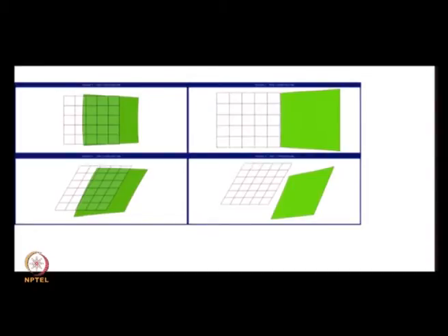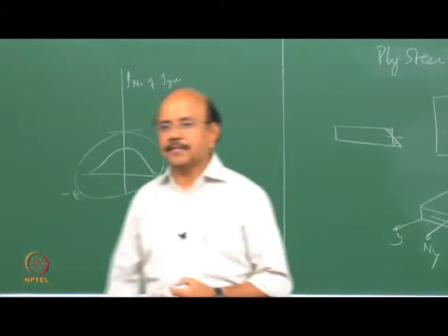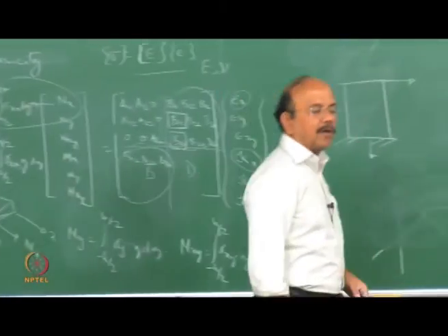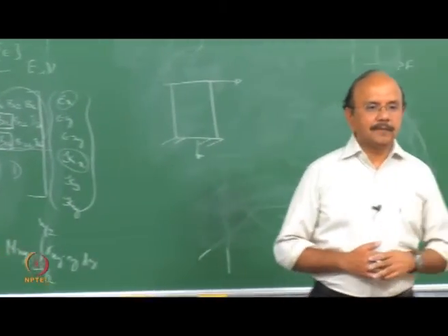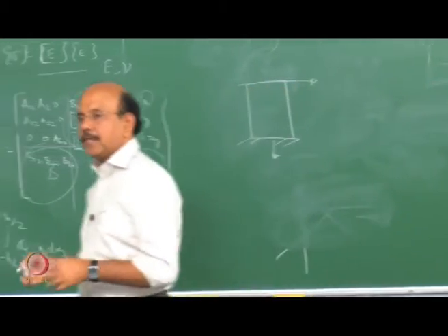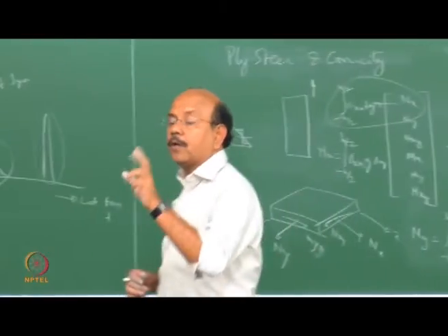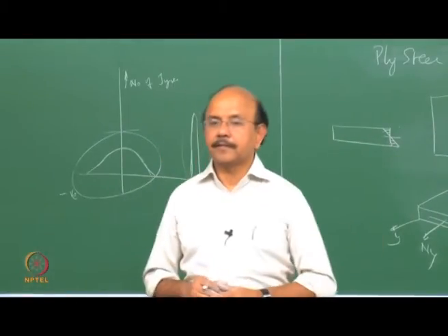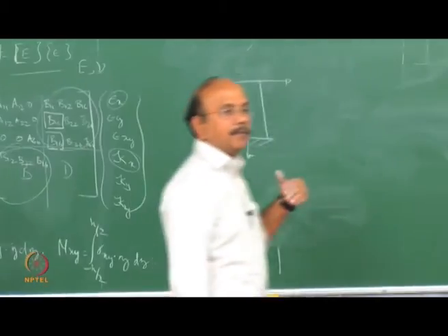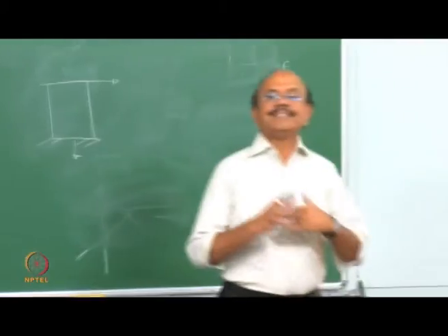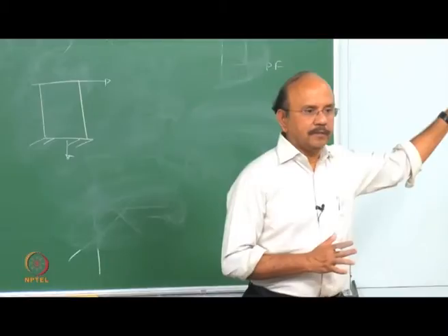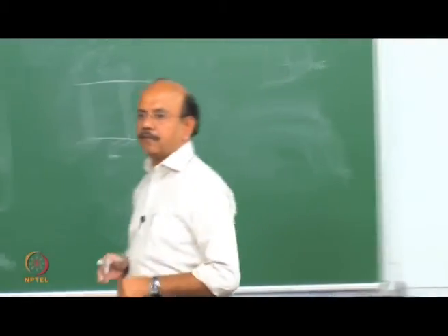Civil engineers long ago recognized this and called it unsymmetric bending. In fact, when you take the next course on automotive structures, we're going to talk a lot about unsymmetric bending. They realized that there are principal axis directions along which there is no coupling. There is a coupling factor involved because I am not applying the force along the principal axis direction, which happens to be the symmetric axes, as you see, for example, in the first picture.